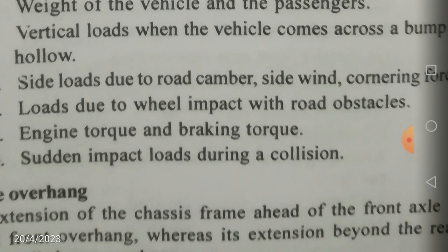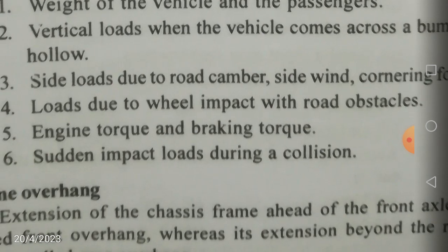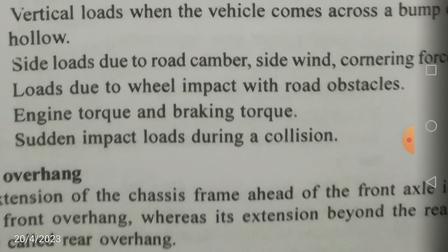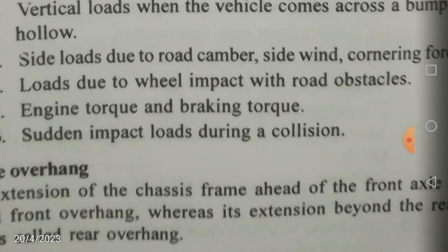So tractive effort is nothing but the tangential force at the wheels, which will try to move the vehicle. Definitely, the force required for this will be coming from the engine. The force acting tangentially at the wheels, multiplied by the radius of the wheels, is nothing but the torque to which your rear wheels are subjected.